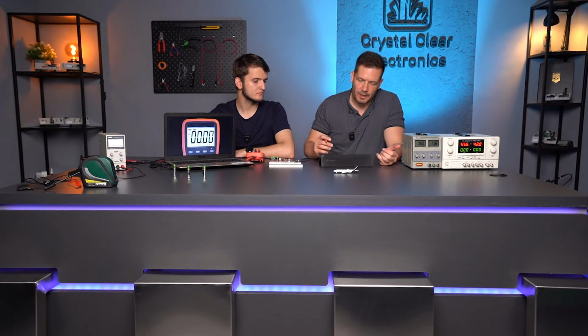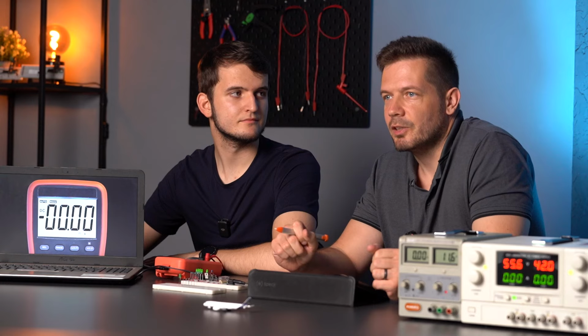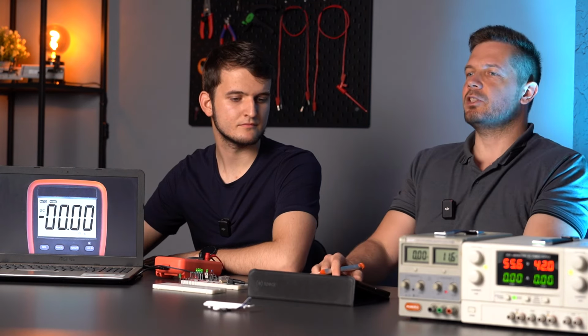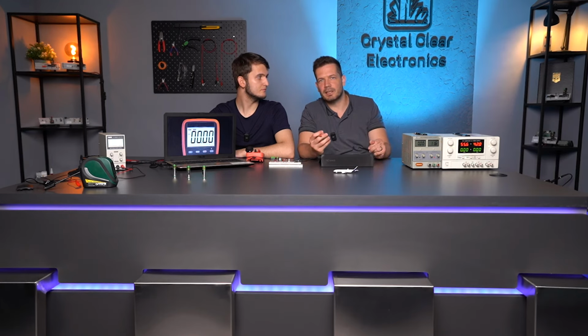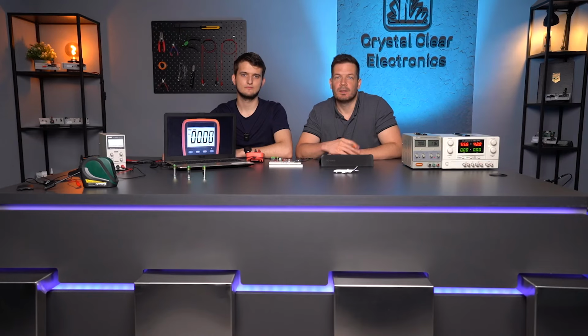Conducts well in forward direction, however its forward voltage is significantly smaller than the forward voltage of the normal diode, and its reverse direction leaking current is excessively low. Schottky diodes are fast switch devices because in them, charge storing doesn't happen. Because of this feature, they are commonly used in high-frequency devices for rectifying, for example, in switching power supplies.